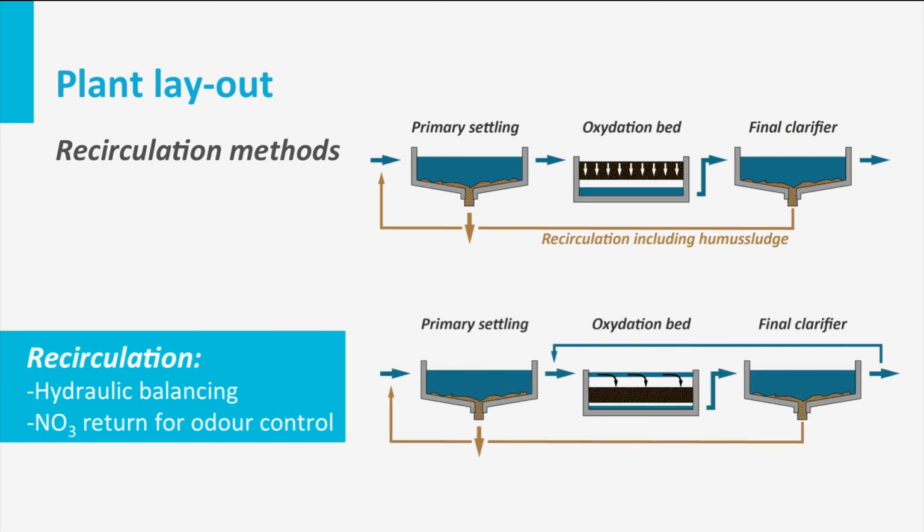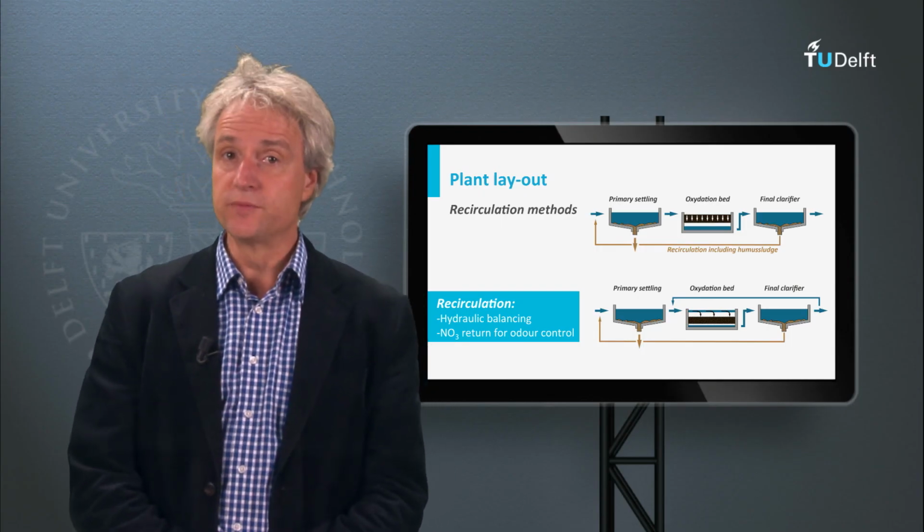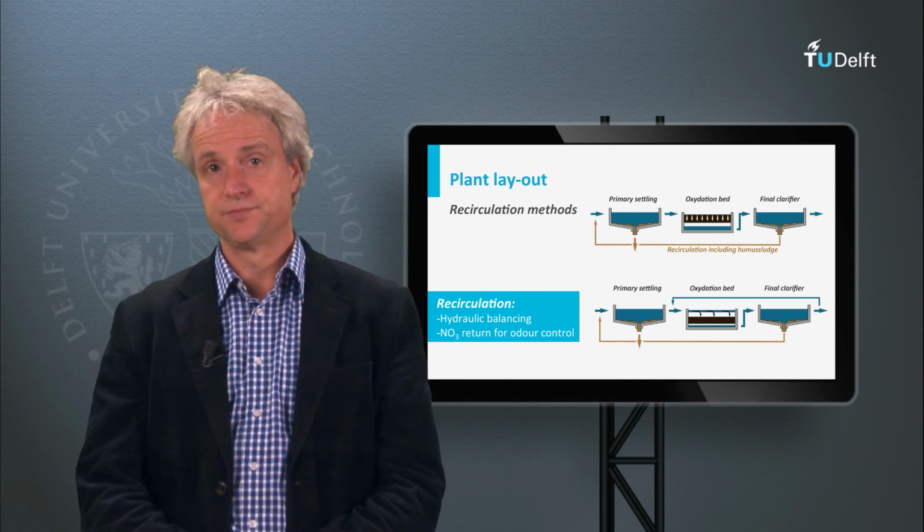Additionally, the nitrified and clarified effluent might be directly recycled to the trickling filter to increase the hydraulic loading to the system and to prevent volatile odorous compounds escaping the filter system. Reduced volatile compounds such as sulfides are then oxidized by nitrate. Effluent recirculation generally leads to improved process performance of the trickling filter.